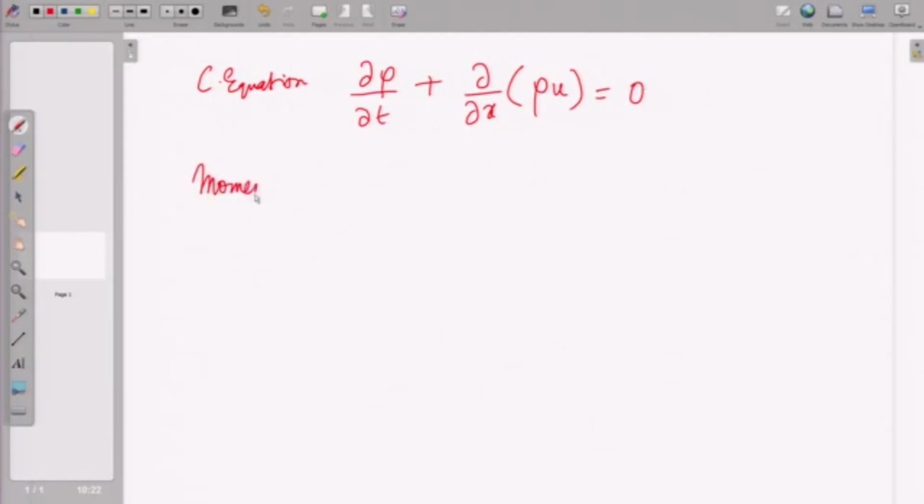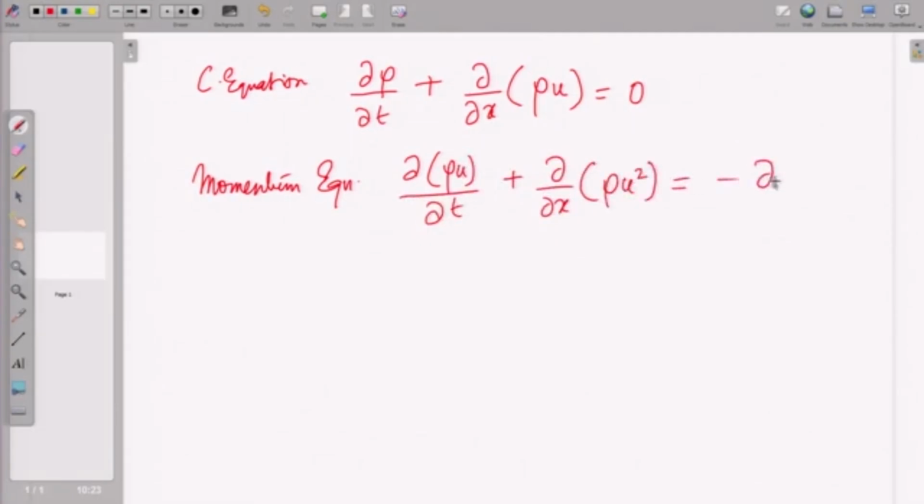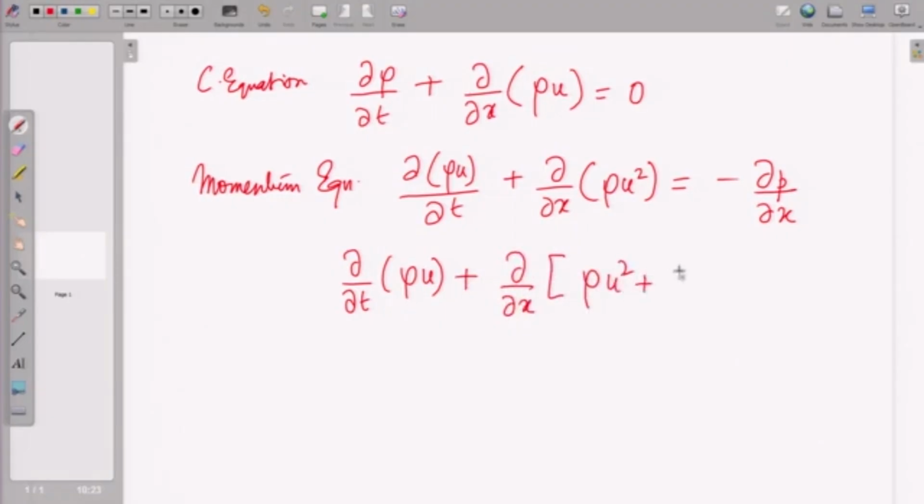The momentum equation. So, as we mentioned earlier that we are going to prefer the conservative form of equations because they are inherently more suitable to handle flow fields with discontinuities like shocks and contact discontinuities, and Euler equations are capable of capturing such discontinuities.